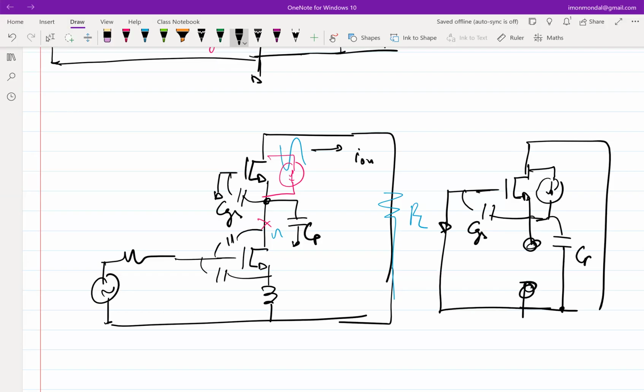So can you comment at low frequencies what's going to happen? What will be the noise output due to this IN? Zero, right? All capacitors are open, the IN will circulate, right?